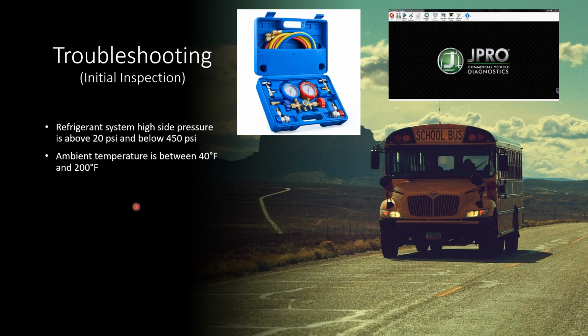For this particular system that we're working on, the ambient temperature sensor is something that we want to make sure we're looking at to further diagnose and help us determine if it's an electrical problem or if it's going to be a refrigerant problem.